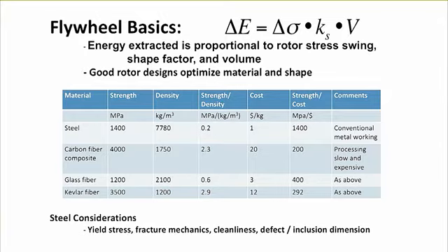What this really says is that a lot of people, when they first hear about flywheels, think it should be heavy, it should be light, it should spin fast. But really what's important is that the material is strong, because you would like to support a lot of stress in the rotor. It takes a little bit of thinking to get through that.